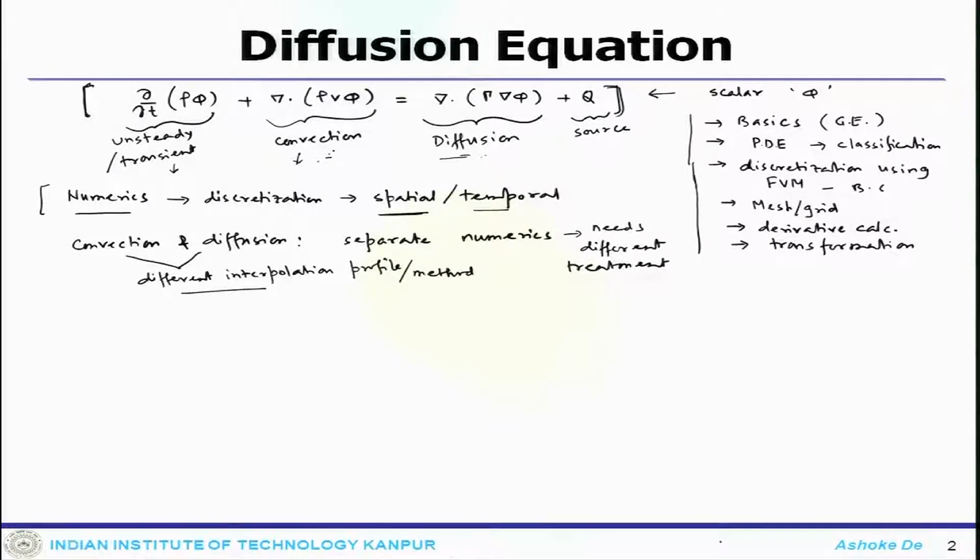do now onwards, since we have talked about all the basic stuff. So, for your CFD calculations, what are the essential components? Your essential components are essentially your grid, or rather you can start with your physical problem, move to the computational problem or computational domain, grid, then governing equations, the PDEs, these are transformed to the algebraic system, and then finally the solution. So, you have all these different steps.